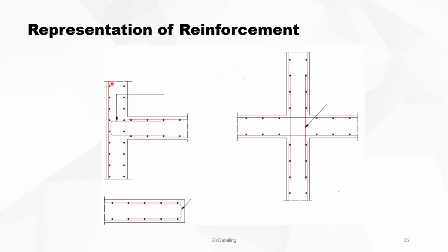This is a typical reinforcement of a wall and a slab. This is the needed reinforcement on the edge of the slab. This is when a wall is continuing in the second level, then you should have the reinforcement of the slab continuously. You put the reinforcement already there before concreting the slab, and then you go on with the next part. This is the lap length of the reinforcement. The same happens here. It's the lap length of the reinforcement.